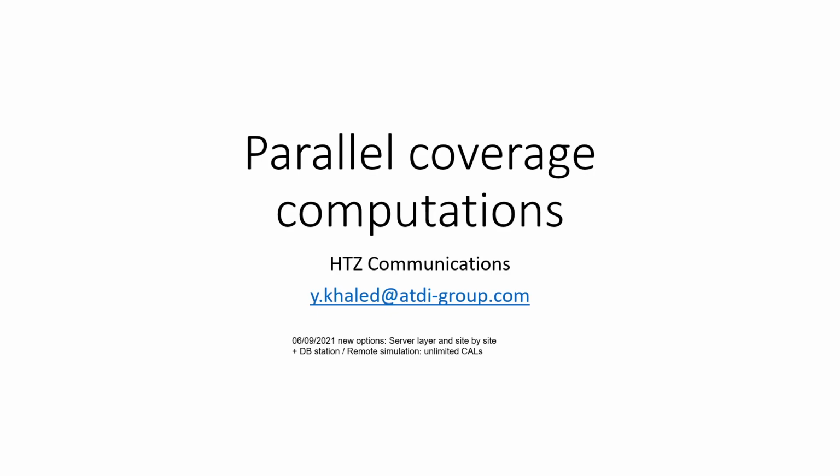Say you have a massive network like 100 or 1,000 base stations or million base stations. Classically, you would run sequential coverage predictions, so site 1 followed by site 2, site 3, and so on. We have a feature in the tool that can actually run coverage predictions for multiple sites concurrently. So you can be doing batches, 10, 20, 30. You can run them in parallel.